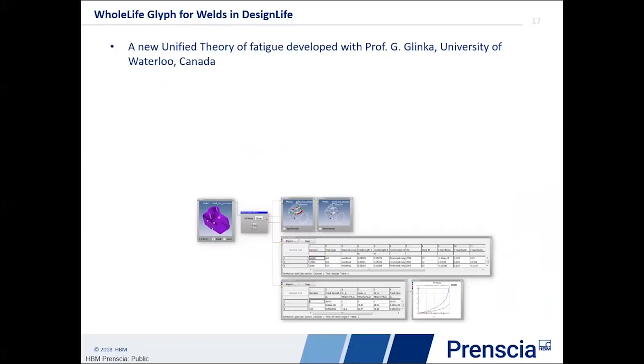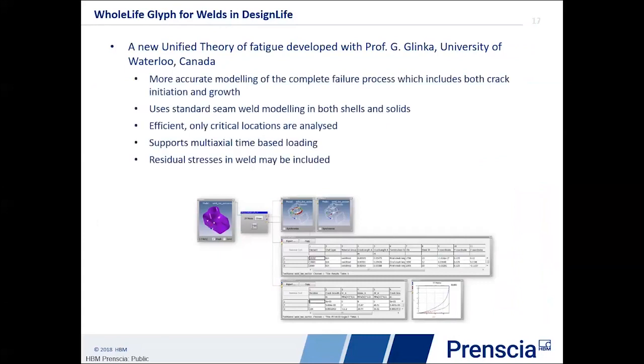What we're bringing out here today and talking about is basically a new capability inside of DesignLife for welds. It's based on a theory of crack propagation that was developed by Dr. Glinka out of Waterloo. And it's using this style of crack growth capability to now analyze welds in more detail. What we've done is taken this and actually implemented it inside of DesignLife,